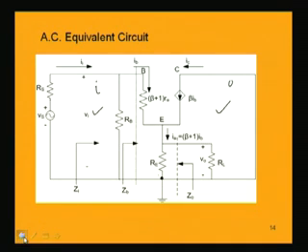So, if we want to find the input impedance by taking the ratio between Vi and Ii, what is Vi? This is the voltage from base to ground, or collector, that is grounded. So, the voltage from this point to this point is Ib into this resistance, that is Ib into (beta plus 1) into re, plus the voltage drop from emitter to ground, and the voltage drop from emitter to ground is (beta plus 1) Ib into the parallel resistance between this Re and Rl.